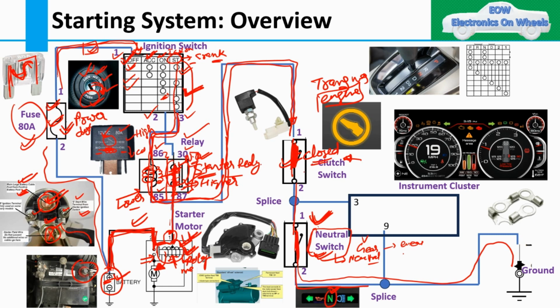There are conditions where you have no need to press the clutch, and if your vehicle is in the neutral state, it will start. But there are some conditions where you have to press the clutch as well, and only then will your vehicle start. So this depends on the vehicle. It is not necessary that the clutch should be pressed every time, but this is one example I am taking. Sometimes you might have faced this condition where your clutch is not pressed and your vehicle is not starting. This is the reason why your vehicle is not starting when your clutch is not pressed.